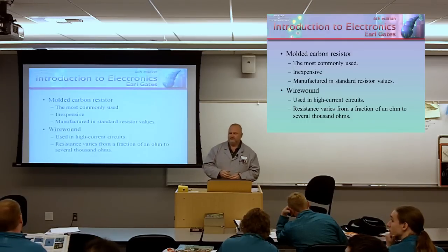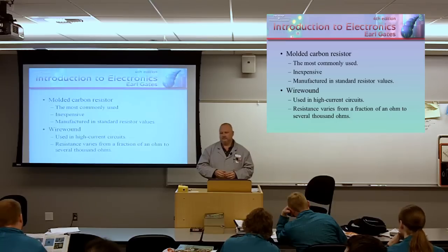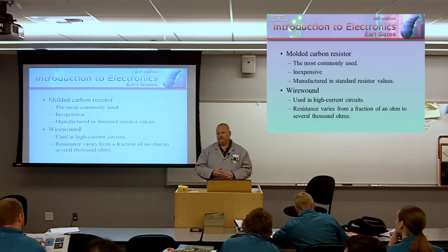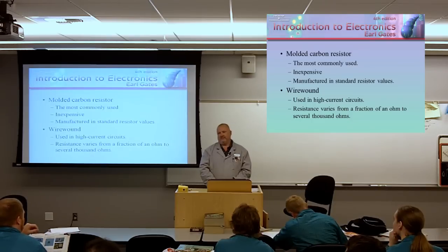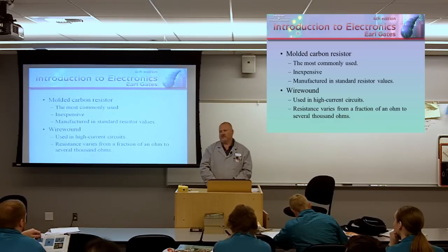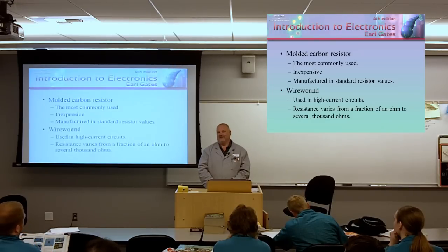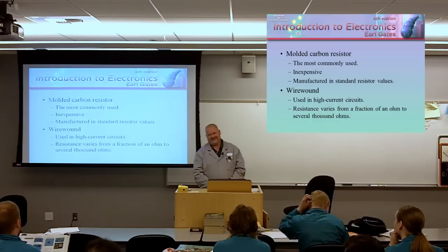Question? When you were talking about the tolerance, and you were saying if you bought a 100 ohm resistor and you found this 103 point something, will that tolerance change, or will that resistor constantly be 103? It could change over time. Typically, it's going to stay pretty close to what it was. But again, since these heat up, things could change in the composition of it and alter its characteristics. But that's not a big factor to worry about. There are a lot more components in electronics that are a lot more sensitive than resistors.